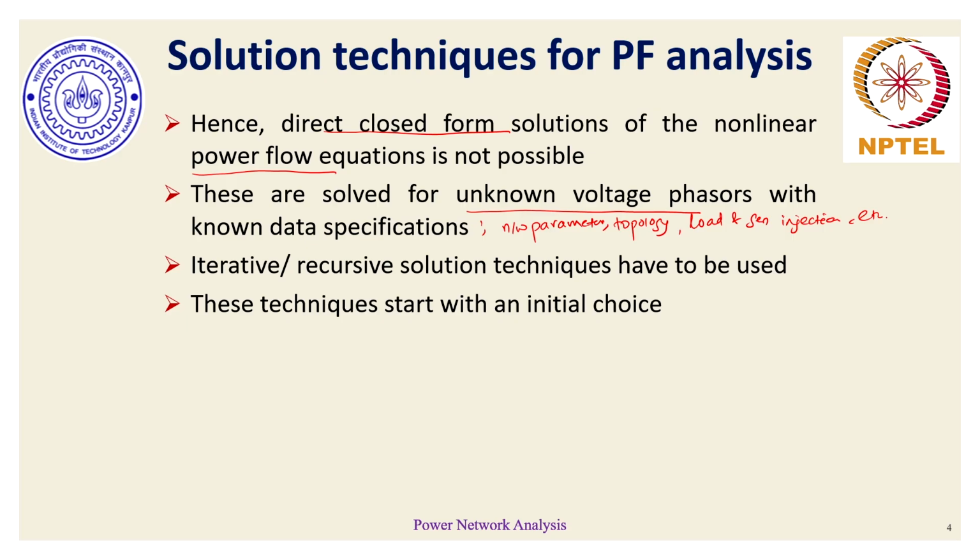And since these are nonlinear equations, the techniques which are commonly available tend to be either iterative techniques or recursive techniques. Each of these techniques starts with some good estimate or good guess of what these unknown voltage phasors would be. Without an initial guess, these iterative or recursive techniques cannot work.